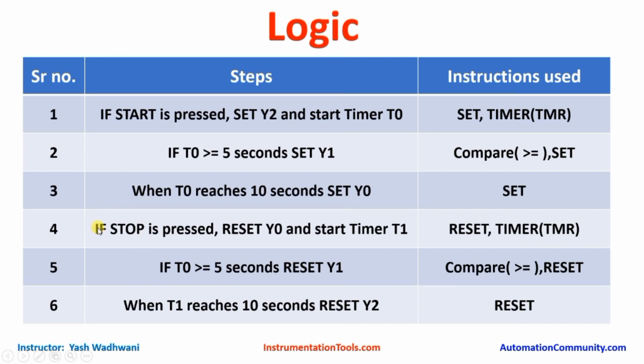If the user presses this stop button, instantaneously my feeding conveyor should be reset or become off. It should also start my timer T1. So for this I have used the reset command and again the timer command.